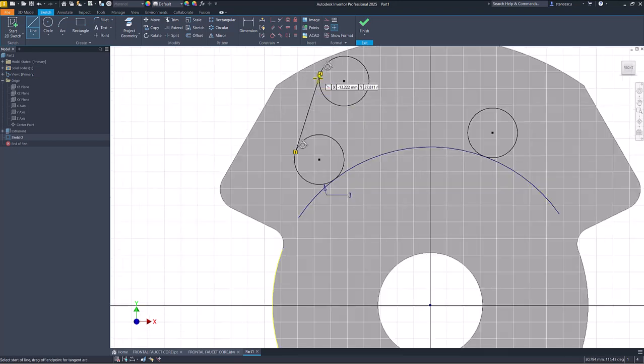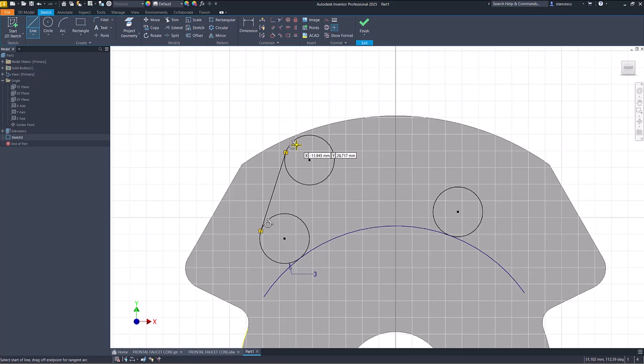I go here and I catch the constraint tangent to the other circle. Be careful, I apply again the same procedure. Keep press the left button, find the tangent, go here and find the other tangent. You see? Then I trim these arcs and these ends of an arc.